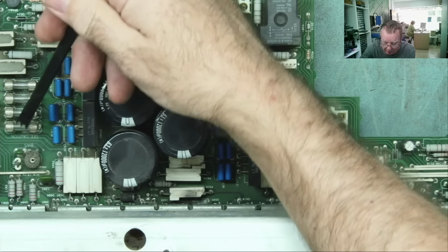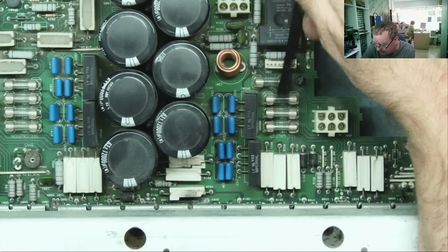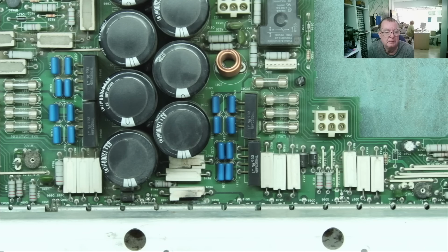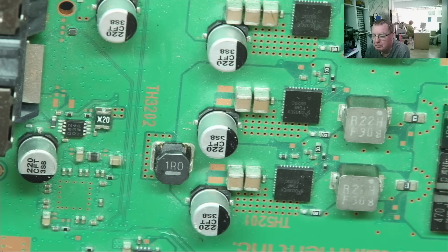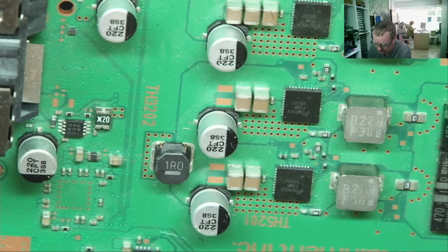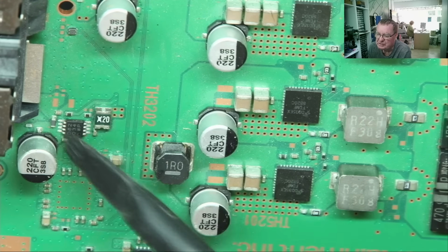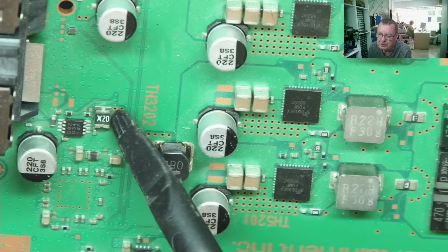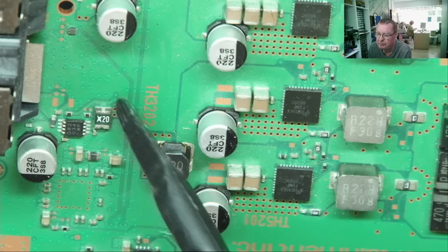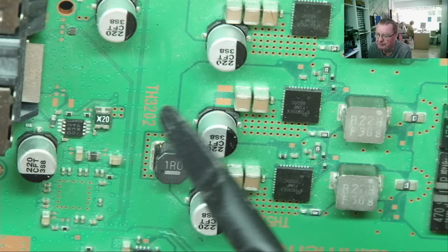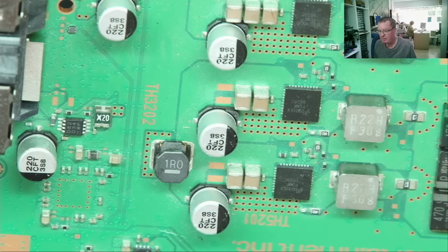I mean, for example, on this PCB we have 8 fuses here, but there's also one further back in the chassis that this came from with a big transformer. So fuses commonly will blow, and they may not look like this. Fuses can come in a variety of styles. We have this style, and sometimes these are not fuses, they're low value resistors, but they look very similar.